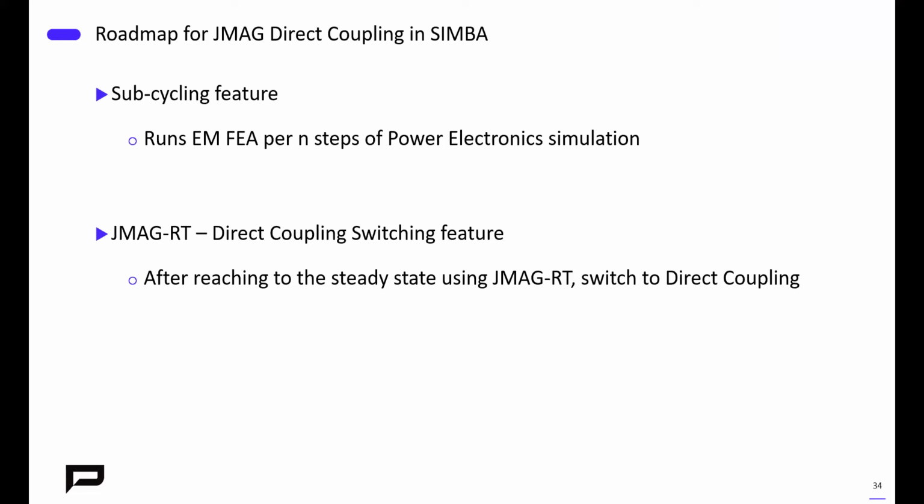There is another question that I can answer. What's the background simulation engine used in SIMBA? Is it SPICE based or PLECS based or something else? It's actually something different, something new that we have developed. It's a solver that can do both piecewise linear analysis like PLECS, but can also do nonlinear Newton-based simulation like SPICE. So the solver of SIMBA is a little bit like one piecewise linear solver and one SPICE solver had a baby together.